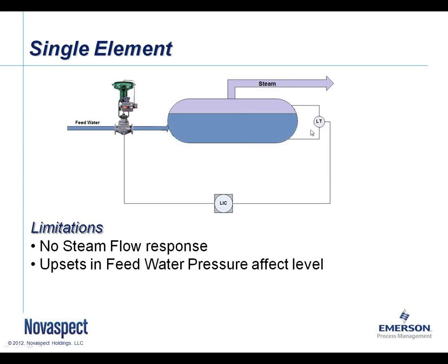I never really recommend using the multi-point devices. The resolution on those will just cause you tuning nightmares because of the 1-inch change between each update in level. The level will have to move either a half inch or an inch, depending on the spacing of the probes, before you change the level. That really causes some problems in the tuning and response of this loop.